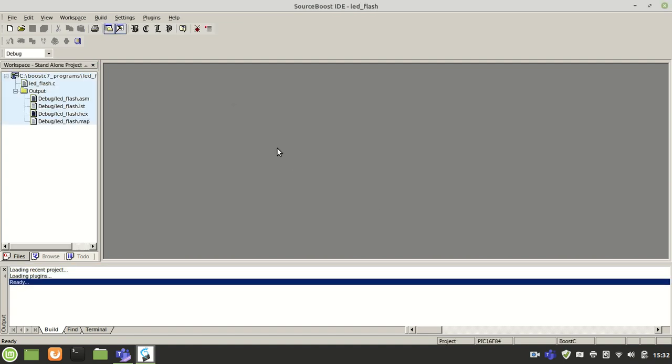Now what's happening is SourceBoost is looking for the last program that I was working on, and the last program I was working on was a program called ledflash.c. Okay? Now in this short video, what I'm going to show you is how you open a project in SourceBoost, how you then open a C file in SourceBoost, and how you compile and link a program in SourceBoost. So let's start off at the first step.